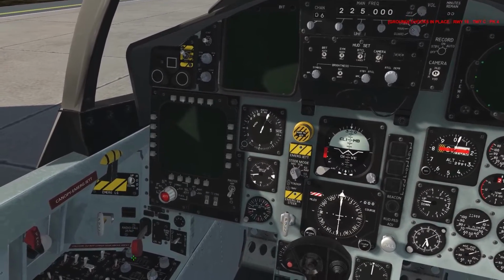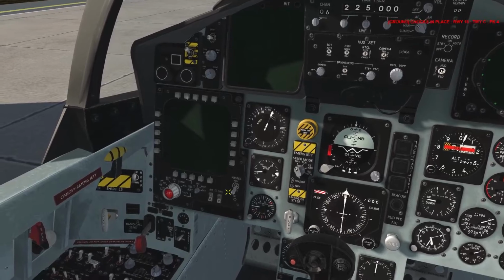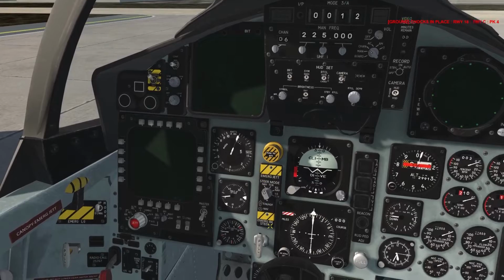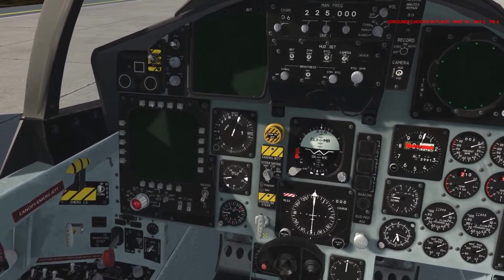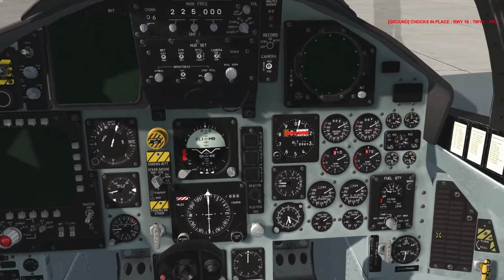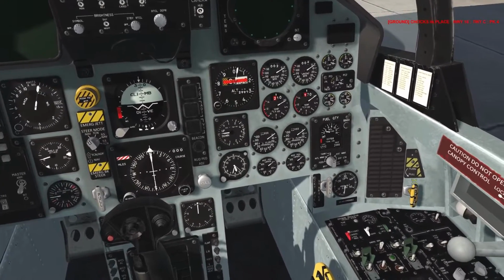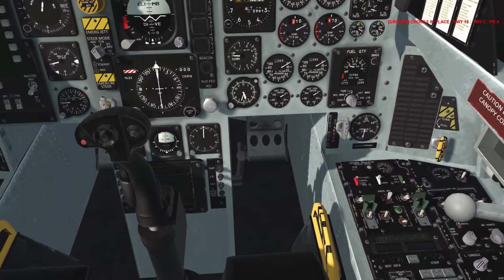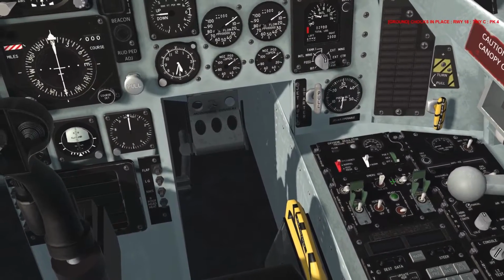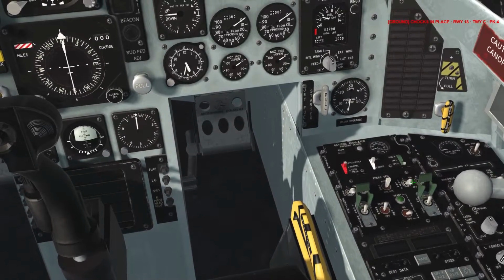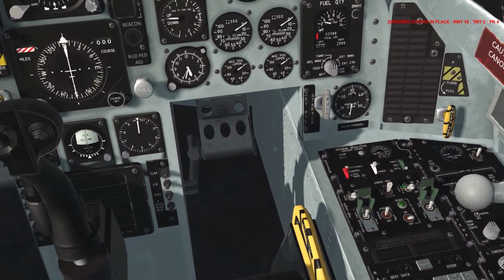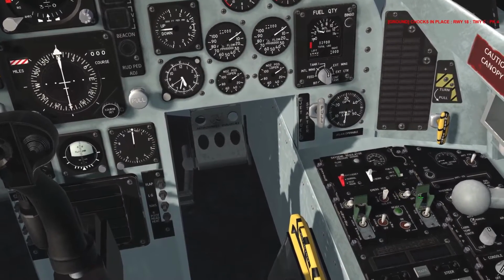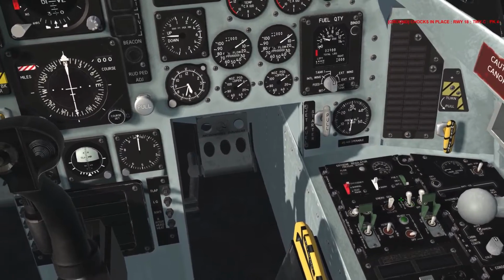Landing gear handle down. The mast arm safe. The emergency jettison button not depressed, and the emergency brake steer is in. Emergency vent handle in and vertical, that's over here, and that is not implemented. So EEC / engine control switch is on. In the cockpit, these are placarded engine control, but they are referred to in some of the documentation as EEC switches. So if you see EEC referenced, just know that's the engine control EEC, same thing. So they can come on via a left click.